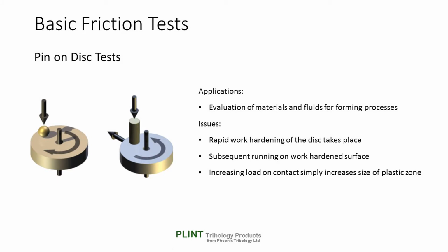A number of attempts have been made to use the pin-on-disc test configuration for evaluating materials and fluids for forming processes. In this case, the typical configuration is to run with a hard ball or spherical tipped pin on a soft disc. The first thing to note is that rapid work hardening of the disc wear track takes place, resulting in subsequent running on a work hardened surface.